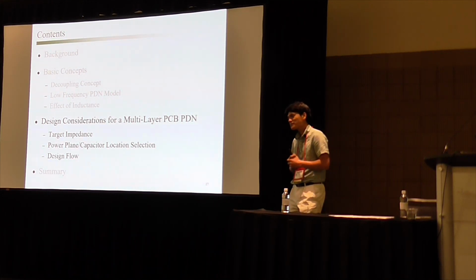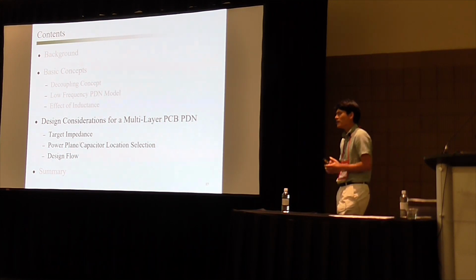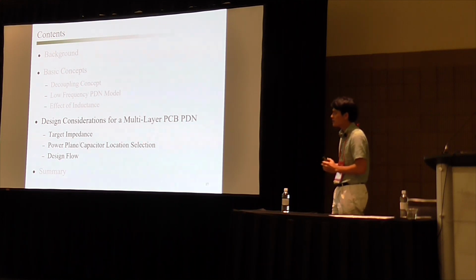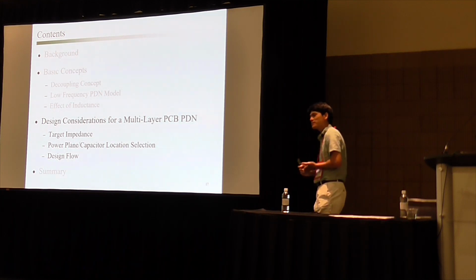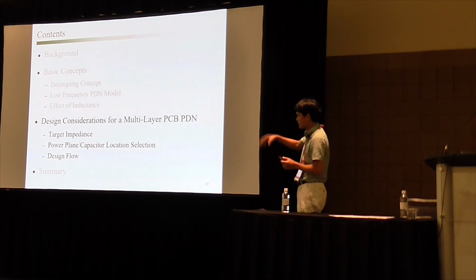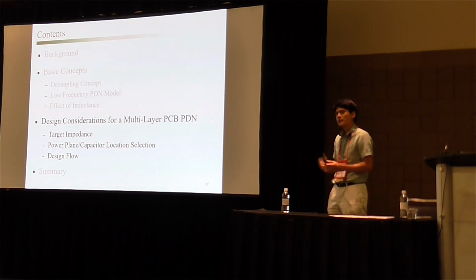What I was thinking is, when we are transmitting some signals and we are putting high frequency capacitors, they have some RC time constant, so there will be charging time. You might understand it this way, but they are pretty small. The RC constant for the high frequency decap is extremely small. So actually, you can think there's no RC delay for the high frequency decoupling capacitors. But at low frequency, the inductance matters. That's why we put multiple decoupling capacitors to cover a wide frequency range.